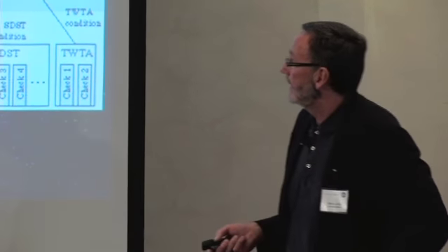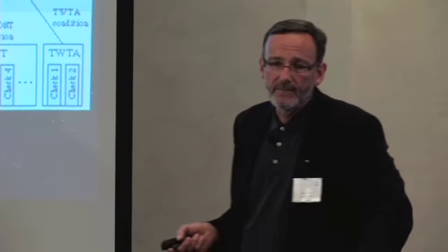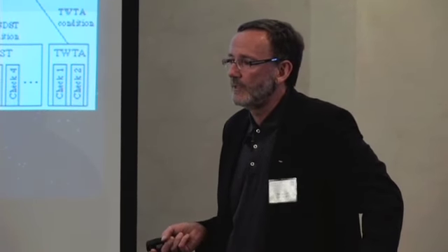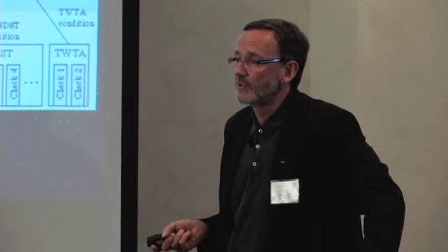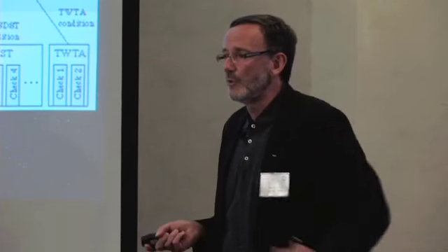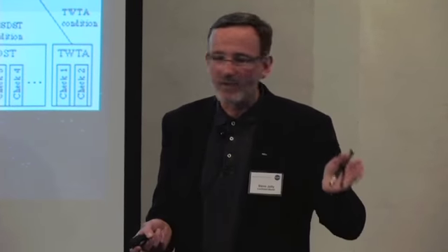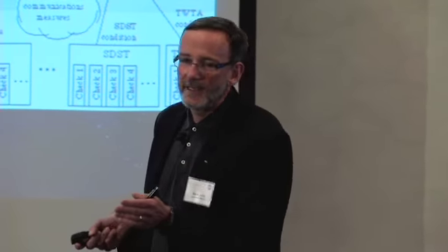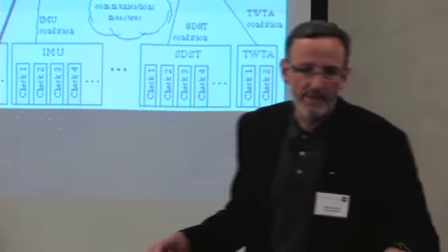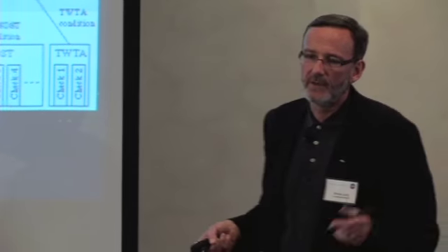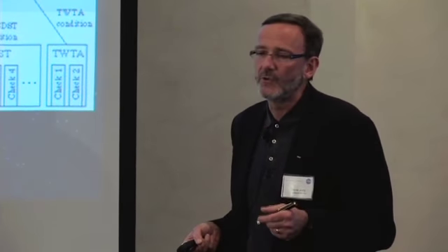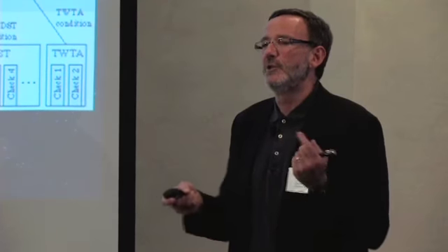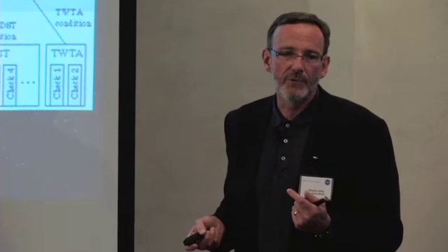Well, on Orion, we've been looking at, and we've experienced on other spacecraft, common cause failure associated with these new electronics and their susceptibility to low-dose radiation. So when you say you have 2 or 3 of the same thing, or even a backup flight computer, if it contains the same double EEPROM in it, you could lose the whole mission. And within our company, there are activities going on right now to figure out how to actually communicate to a spacecraft that has lost all of its computers.